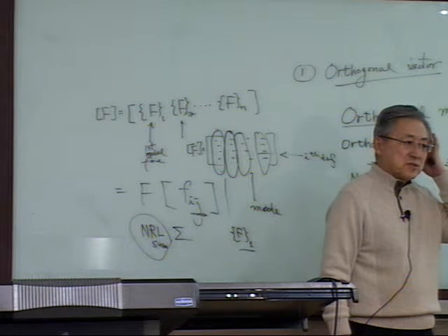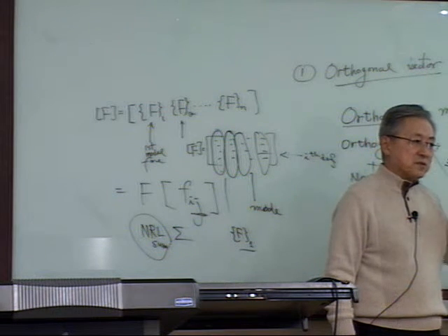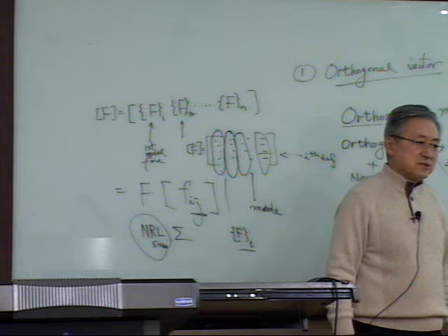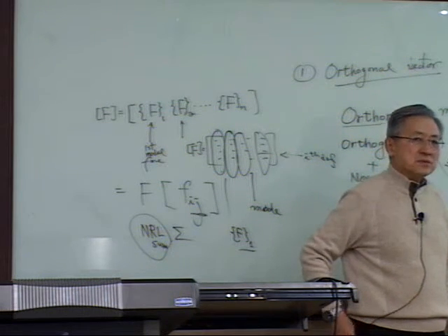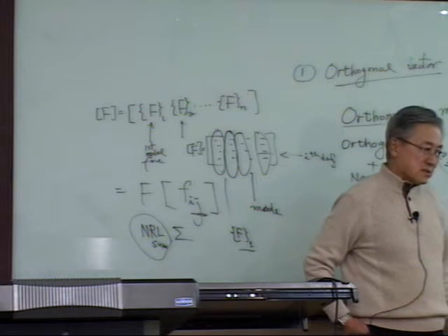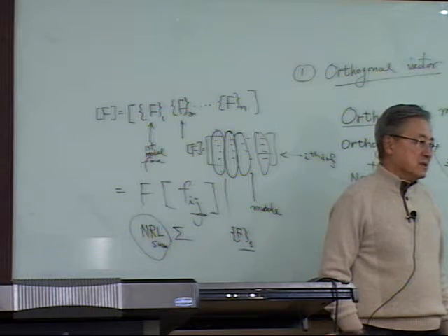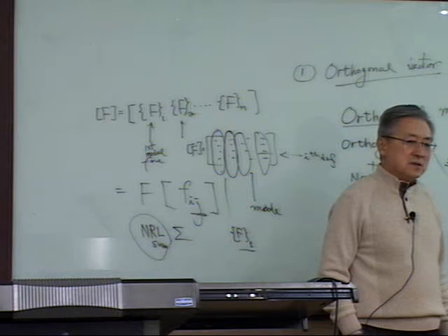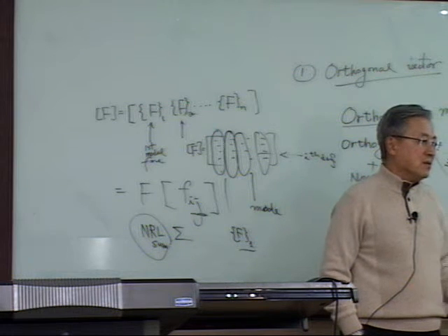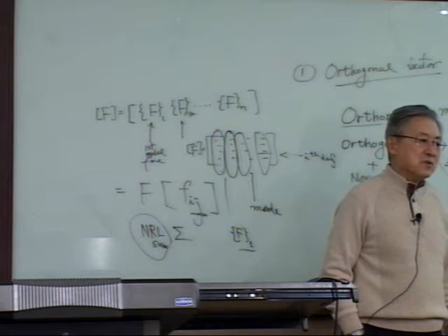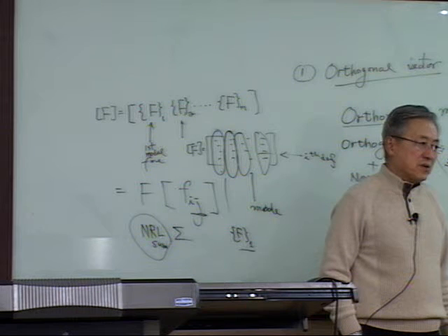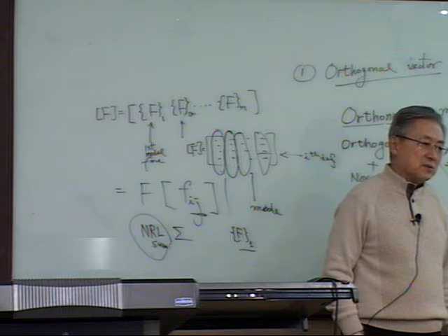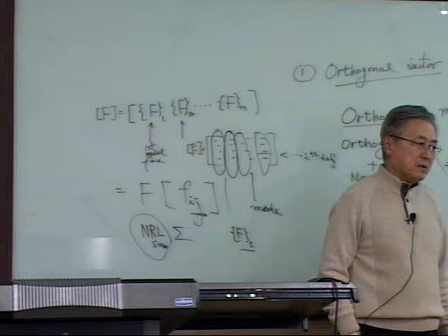You multiply by 6, you will get roughly the number of degrees of freedom, which is 600,000 degrees of freedom. How many modes do you expect? 600,000 modes. Are you going to apply all 600,000 modes to do all the modal summation? That's ridiculous. You are not going to do that. Then what to do about it? How to do about it?